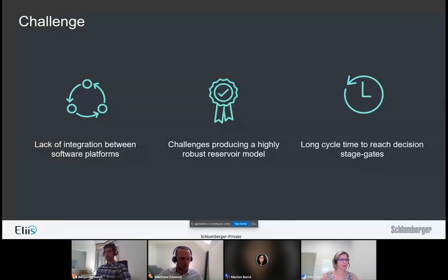I've got another question for Matt. How can I get access to the seismic stratigraphy process in Petrel, and with which version was it released? Yeah, this is a good question as well. So this comes as part of the core licenses in Petrel. If you have access to structural framework, you'll have access to the process, and you can select that by right-clicking on a subsurface framework.